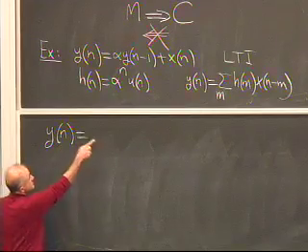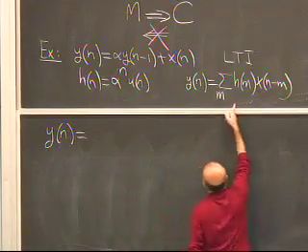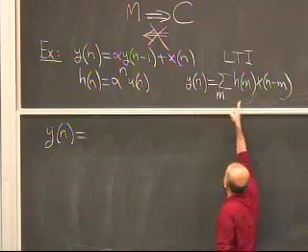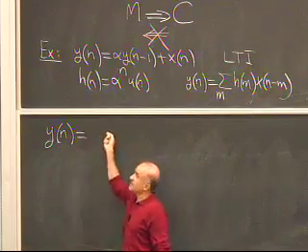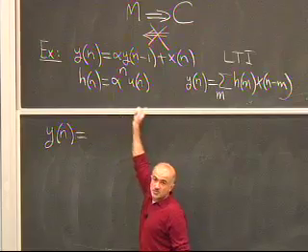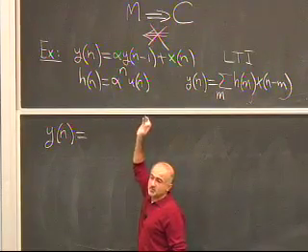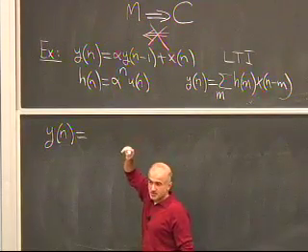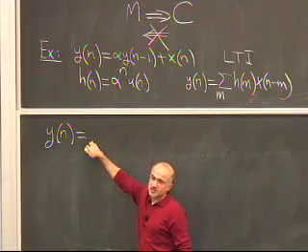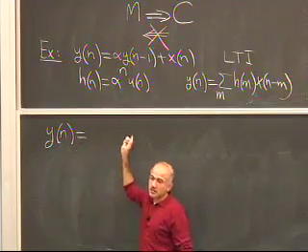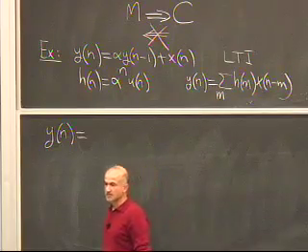What is the output in terms of the input? I want you to plug in the expression we have for the impulse response into the convolution expression and write y only in terms of x. That difference equation relates the output y with its recursive form or description of the system. I want you to write an expression that's only between y on one side and x on the other side.